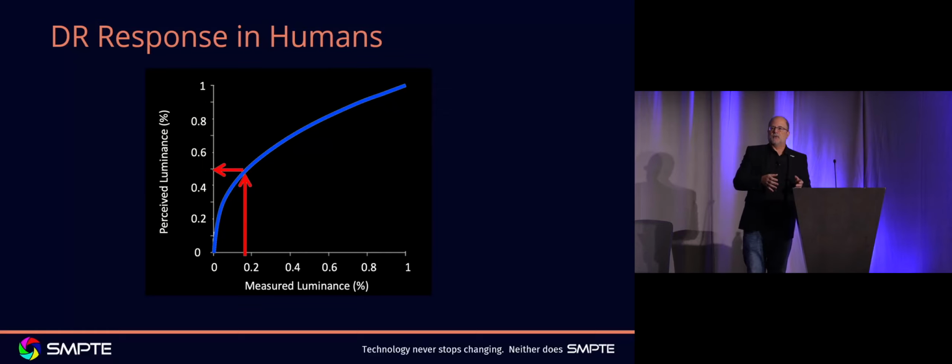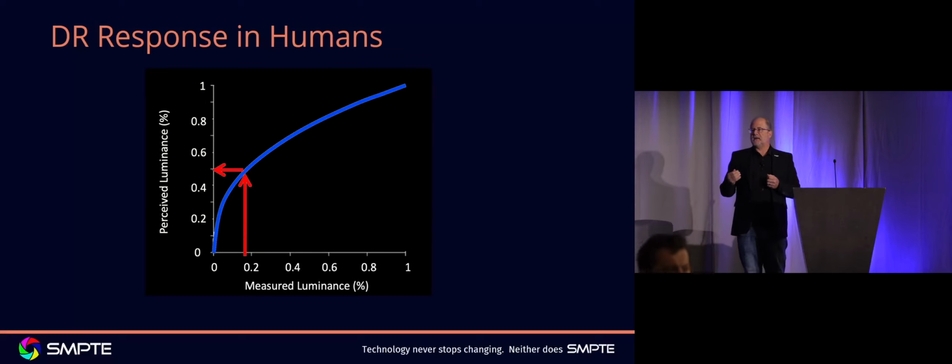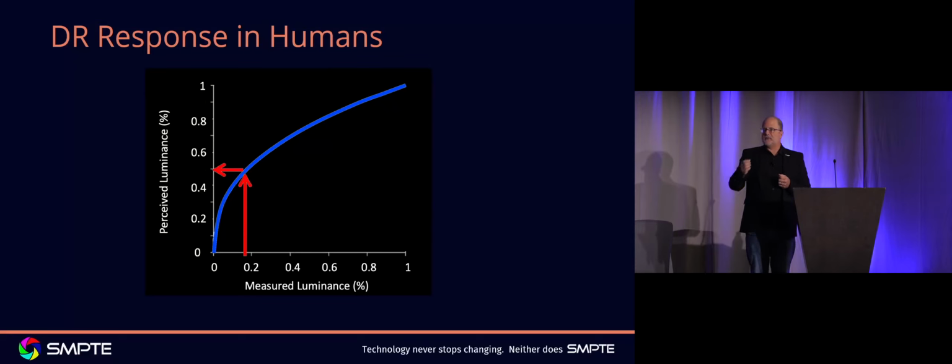If you want to go into higher dynamic range for a capture, we're going to go to 12-bit if you use a logarithmic space. Like I said, human perception not being linear, you can have more code values at the beginning, fewer code values at the end. So that's a logarithmic function. By using 12-bit logarithmic, we're able to capture a lot of dynamic range. This is, for example, every RAW is 12-bit, and a lot of other cameras are.